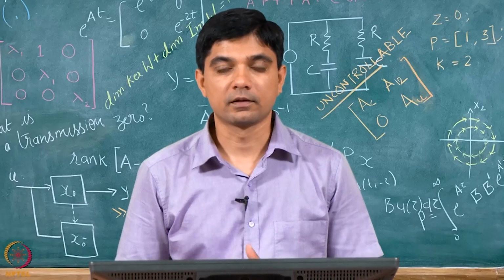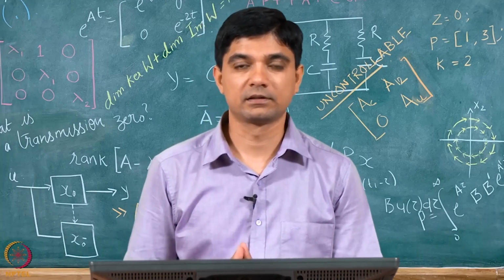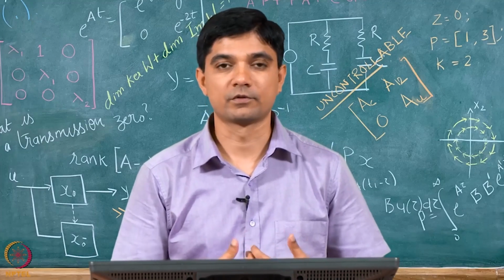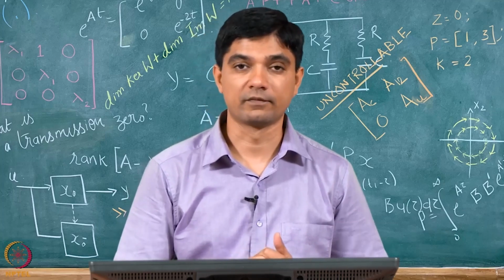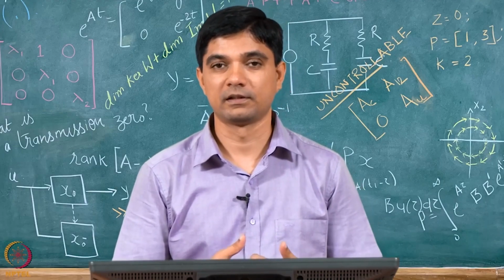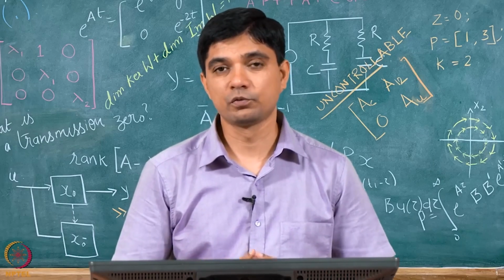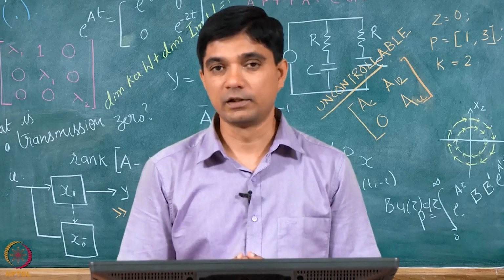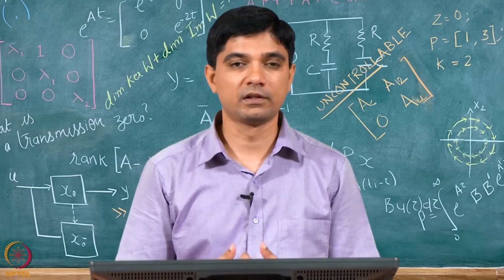Okay, hello everybody. So this is a little supplementary material to lectures on week 6, where we essentially defined for ourselves the concept of Lyapunov stability and conditions to verify stability in terms of eigenvalues and some other LMI-like condition, like A transpose P plus PA is minus Q and so on. In the proof of one of those, we had used something called the comparison lemma.